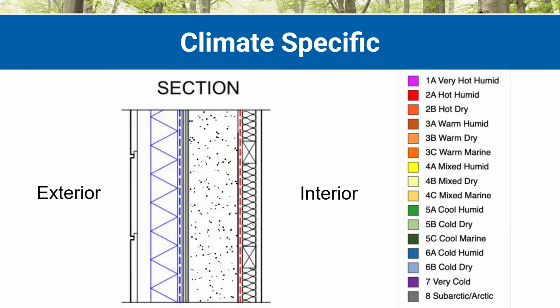And here we're showing a service cavity, a little chase for you to run your electrical components inboard of that Intello membrane so you don't have to air seal all around it. But it also gives you the opportunity to include a batt, additional R value in here, and then our drywall. So kind of talking through how this assembly would be changing. In our hot, humid climates and climate zones like 1A, 2A, we really do want to prioritize this exterior air barrier, and we want to make this a class 3 vapor retarder.